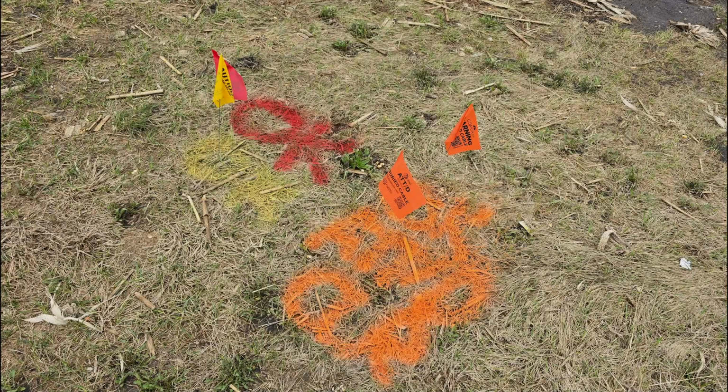The paint on the ground shows that there's been a check for buried utilities before digging. The different colors will show what companies have been out checking. There could be electric, there could be buried fiber optic, there could be gas lines, and all these things have been marked prior to digging, and it's really easy to make this check. All you have to do is go online or make a phone call.